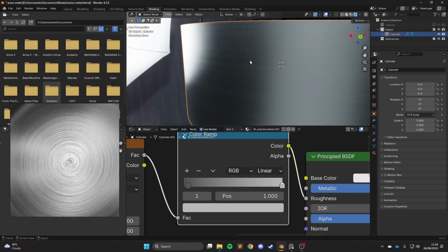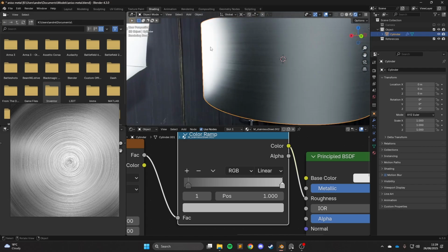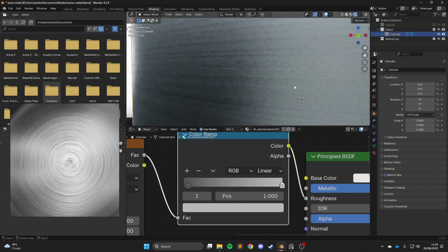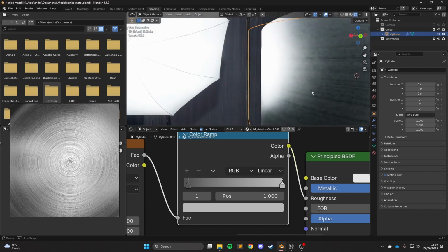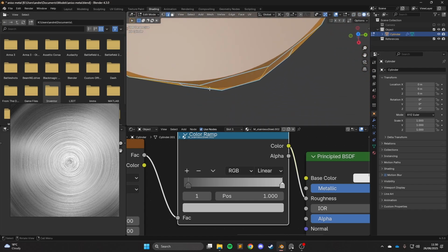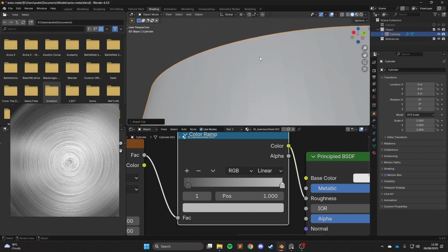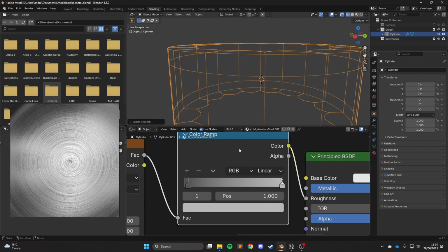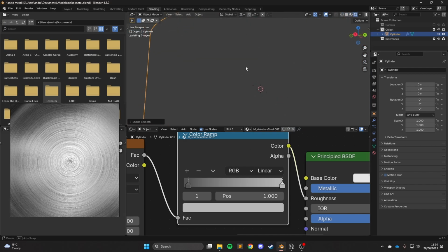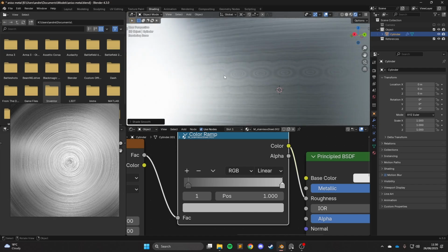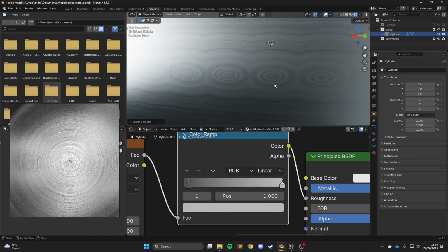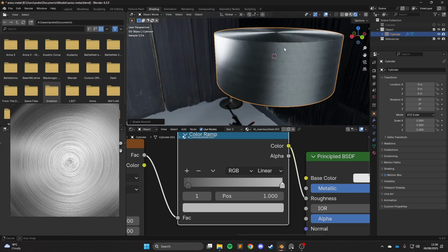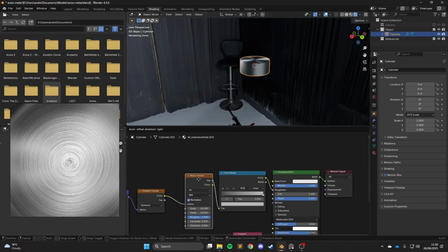So we can technically just use this, but the only issue is because we're using the sphere's radius. If you can imagine, there's a kind of vector going up here, but there's also ones coming out here, and because this is a mesh that's got technically still flat surfaces, if we shade flat, you can see these are sort of flat. You can kind of see here, despite the subdivision. We've ended up with, if we let it render, yeah, we've ended up with these here. So effectively this is staring straight into the radius of the circle, and it's sort of creating these extra turn effects up here. So there's a way to get rid of that.